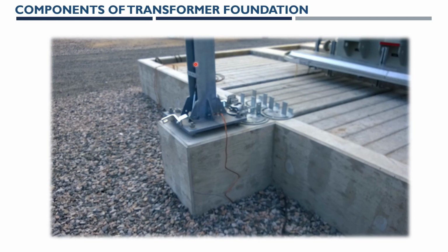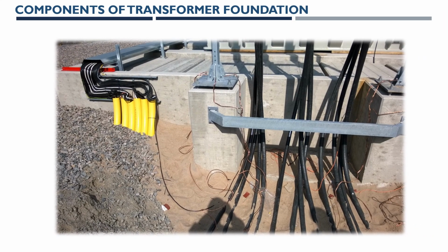And this is an equipment support which is mounted on the transformer bund, and this is another view of equipment and cable entry to the transformer. So this is a protected cable zone. Here you can see some earthing cable, which is bare cable, running to the ground, and these are the cable trays running towards the transformer foundations. You can see these are the precast concrete elements for grating, and these are the bund walls which are also holding the equipment support.